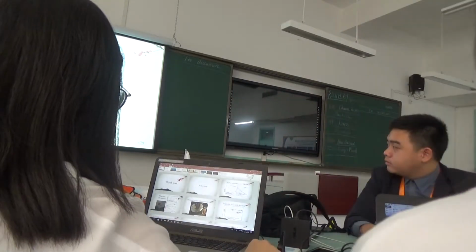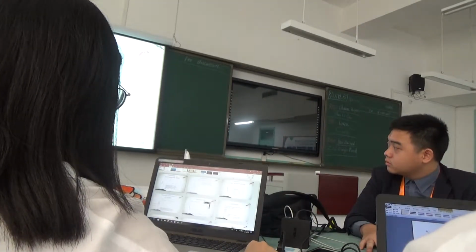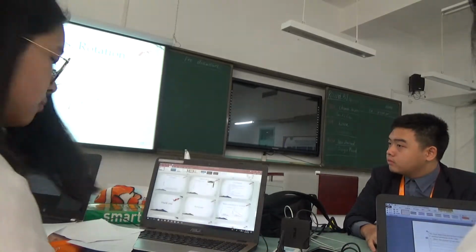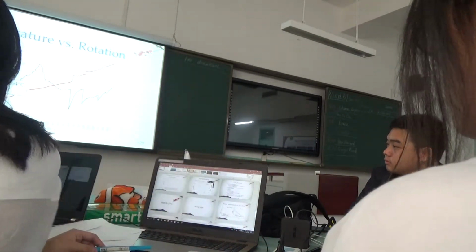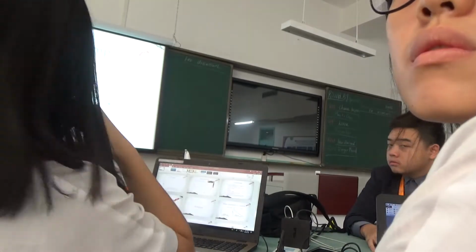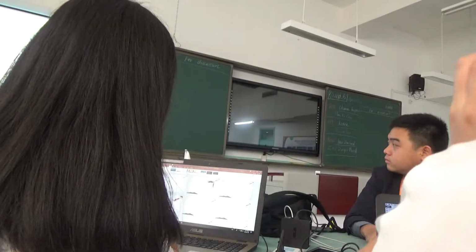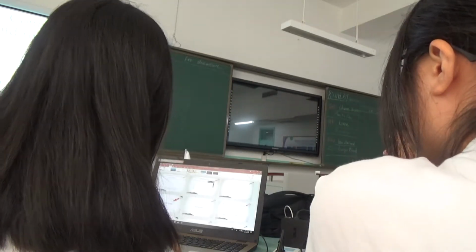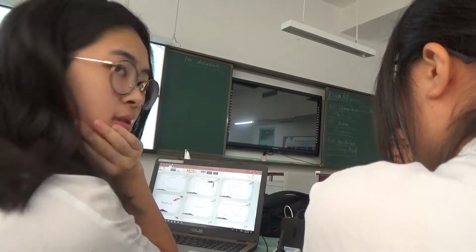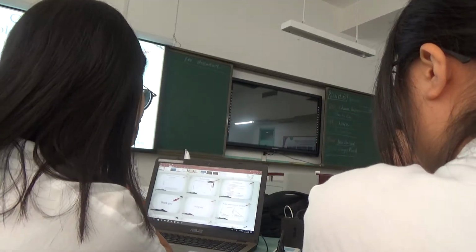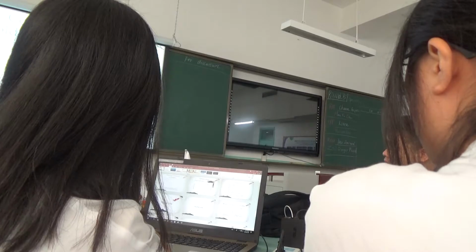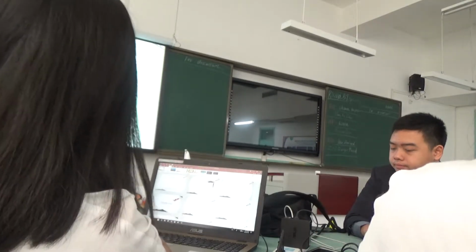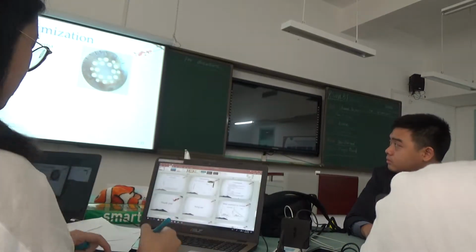And we can see the initiation of its rotation is at 164 degrees. The first jump is at 257 degrees, which is both lower than the Curie point. So our actual Curie point engine rotates under the Curie point. And then we investigated different temperatures of the water tank under it and its continuity. We can see that appropriate cooling can improve continuum percentage, so it's not necessarily a lower temperature of the water tank that will have better continuity. And also we can see when we put a 48-degree cold reservoir, it also has less deviation of angular velocity, indicating that it rotates more steadily.